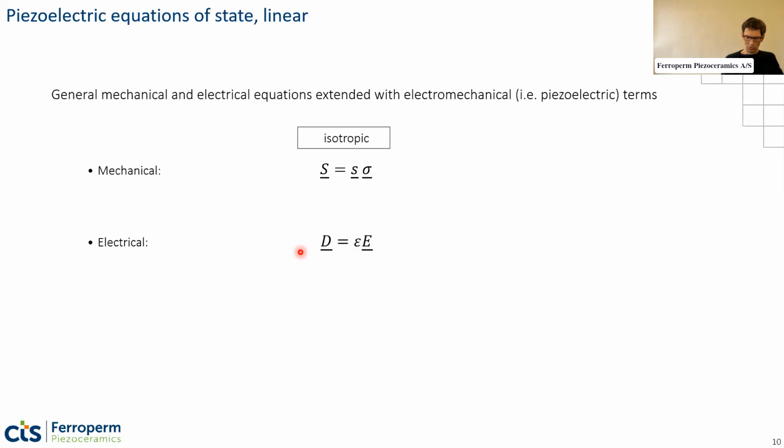So what I want to show now is that for these materials that we are talking about, it becomes a little more complicated. To begin with, if it's an anisotropic material, the equations look the same, but instead of 2 coefficients in this S tensor, it can be, in our case, 5 coefficients, and for a complicated crystal, it could be even, I think, up to 21 coefficients. But in our case, we need 5 coefficients instead of 2 in the isotropic case.